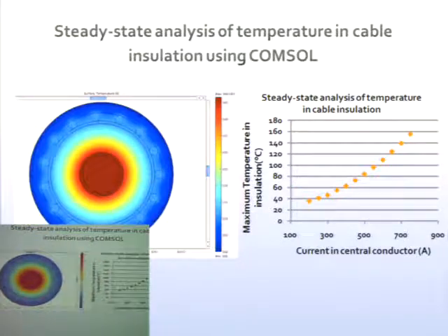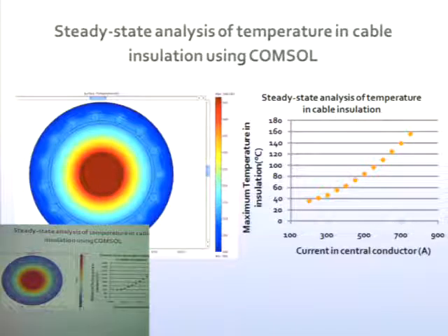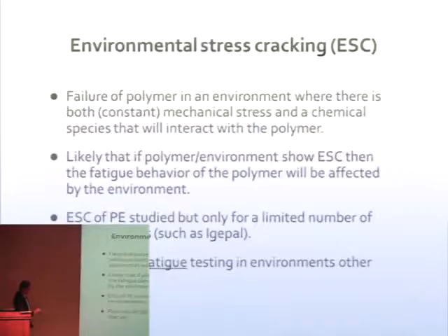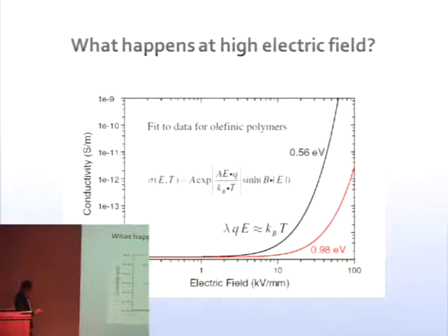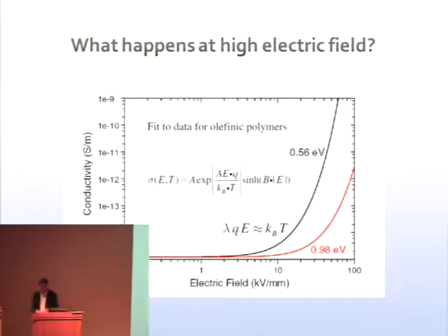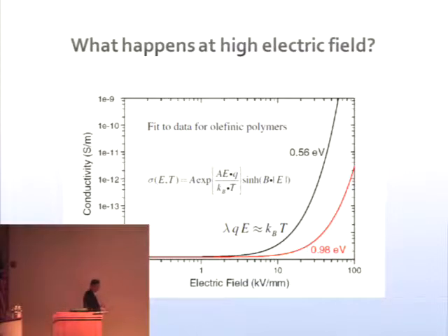Right? Now, the other issue, which is the space charge issue, is that the space charge limited field for polyethylene is around 250 megavolts per meter. So, at that point, also the calculation as you did it is no longer terribly valid because...